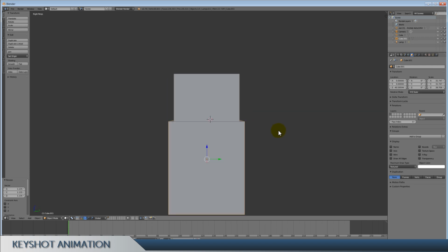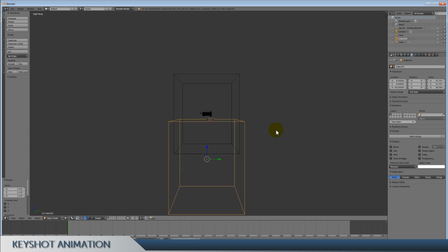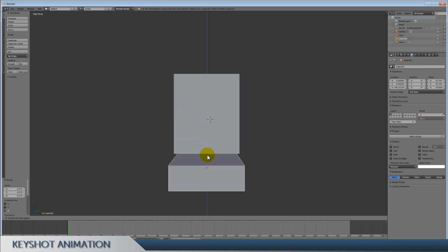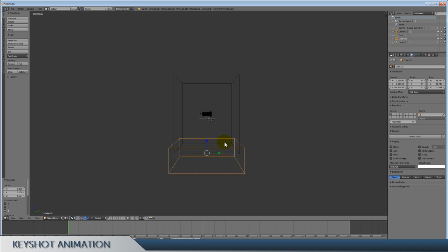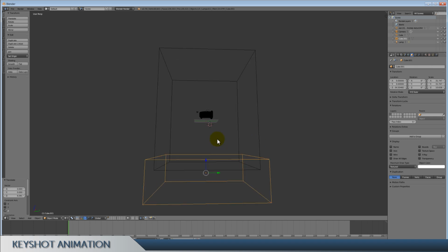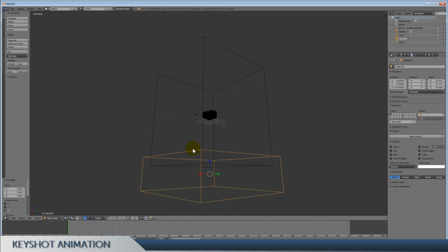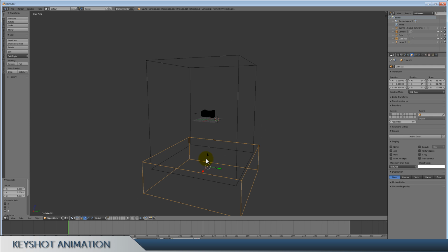And let's bring back some side view, and I'm gonna again go to this wireframe mode, and I'm gonna scale this cube right now only on the Y axis. I want to make it small like this. Now I'm gonna press Y again to go to this type of view. The only thing we need now is to move it so that it slightly intersects this other cube, and as you can see it does intersect. That's the work done. This second cube is gonna be our outflow object.